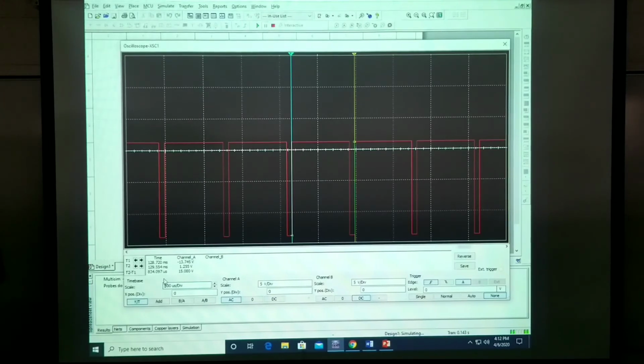So we punch that into our calculators. Do the reciprocal to find your frequency, which I found at 1.12 kilohertz.